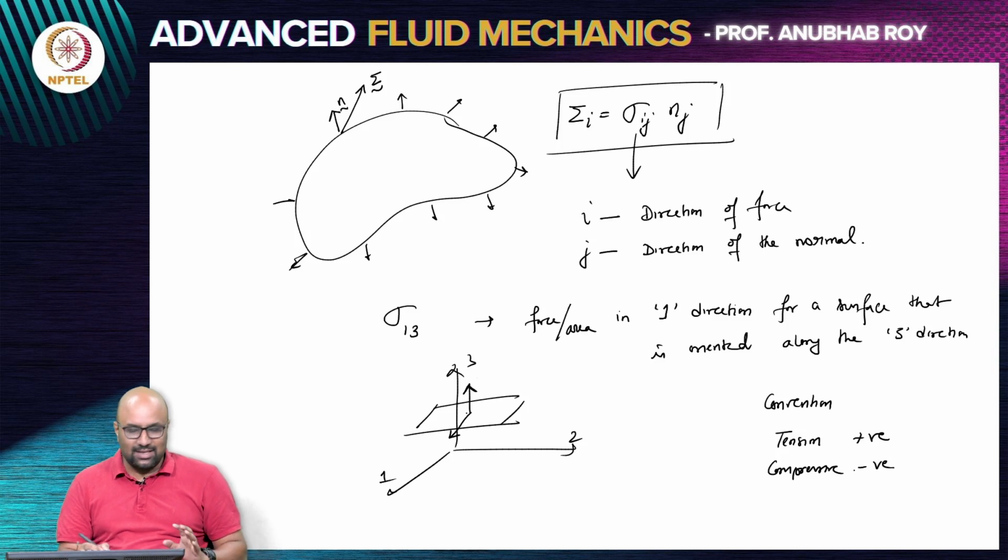So, now we are relaxing this, or we are basically saying that in general, surface forces are not always going to be tensile and compressive. There is an additional part of surface force that will come in, where the surface force can be perpendicular to the unit normal, not necessarily aligned to the unit normal. So, this introduces an important idea that we will get forward, is the idea of shear. Shear is what we are doing in many scenarios in day-to-day life. You place your hand on your bench and you try to slide your hand. What you are doing is you are trying to shear the bench surface.